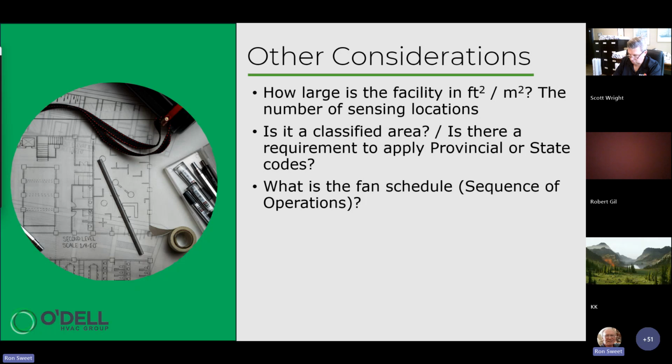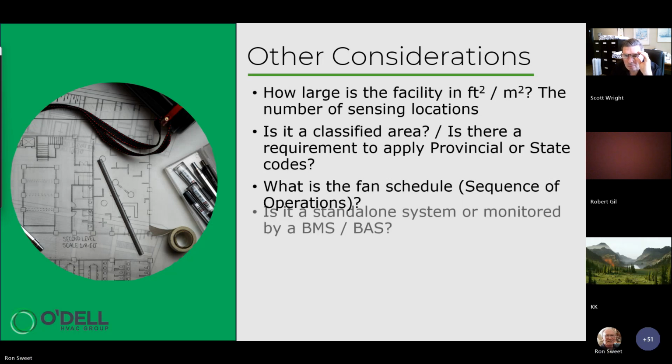You typically wouldn't have that fan on. That fan would only come on if they were charging the batteries, and it can be controlled with a gas detector, such that you can set that gas detector to operate audible and visual notification appliances should that concentration rise faster than that fan can dilute it. So that's something to keep in mind.